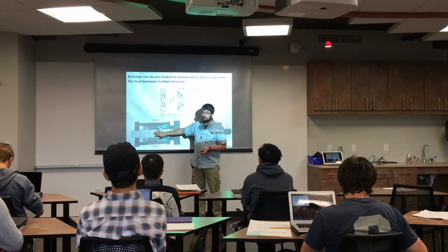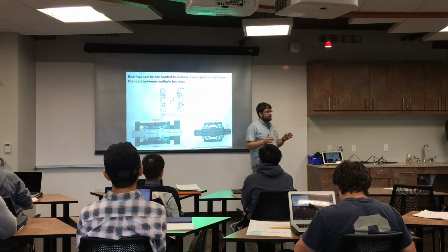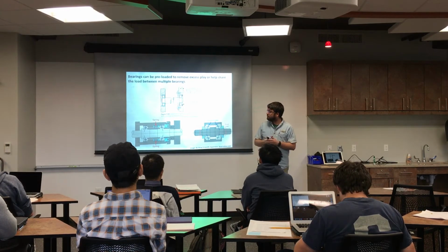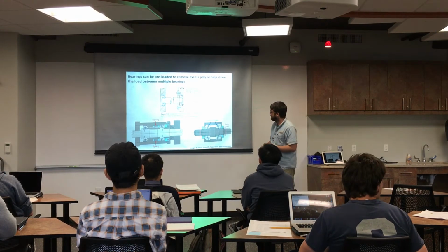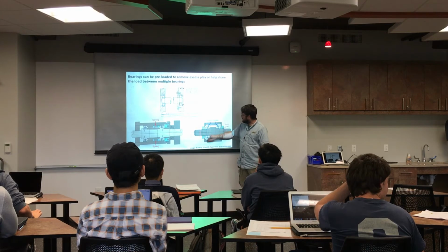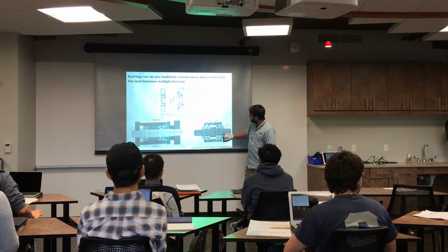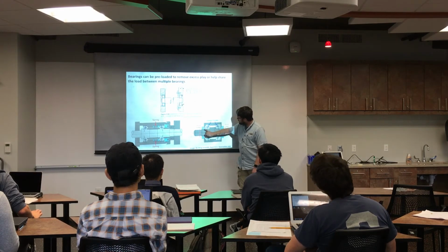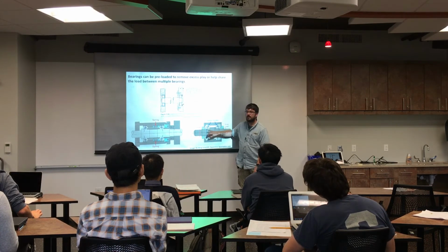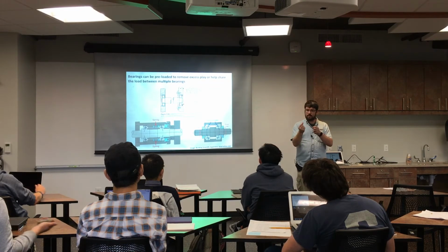You've got springs that are pushing on the bearing to take the play out. That's really great because, say, if your part's going to experience significant thermal expansion and contraction, those springs can help take up a little bit of that. Whereas maybe the cheaper way is by using a solid preloading device. So here we've got the bearings, and then we've got these nuts that are screwing in on this threaded rod to push on it and preloading the bearing so that play is gone.